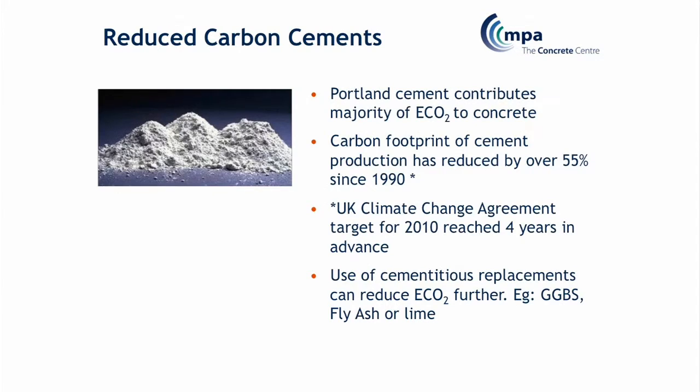You note there as well, aggregates 4 is very low in embodied CO2, and reinforcement 427. As I said, the industry have been doing a lot to reduce the embodied CO2 of cement, and in fact it's reduced by, I think, over 55% since 1990. The way they've been doing that is to use alternative fuels. That's a big key part of it, so using waste to burn to make the cement. So that's good news.